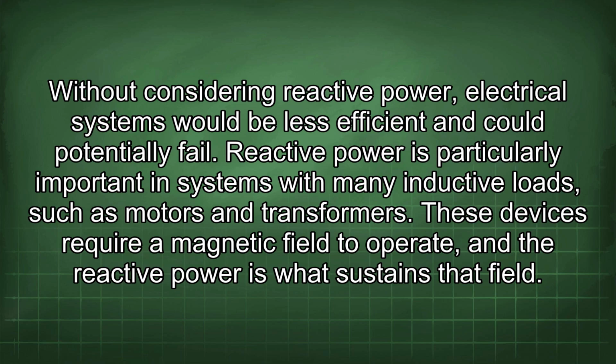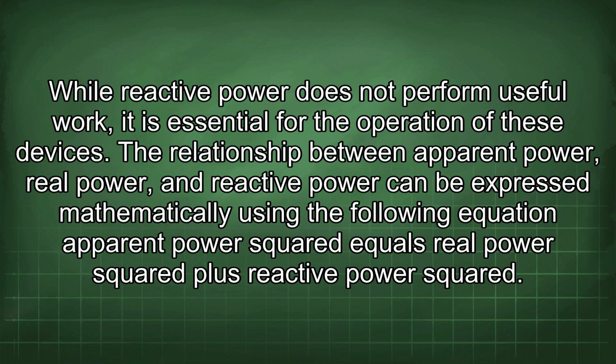Reactive power is particularly important in systems with many inductive loads, such as motors and transformers. These devices require a magnetic field to operate, and the reactive power is what sustains that field. While reactive power does not perform useful work, it is essential for the operation of these devices.